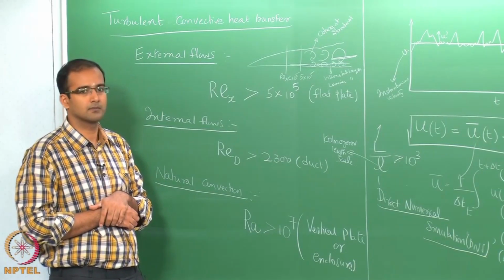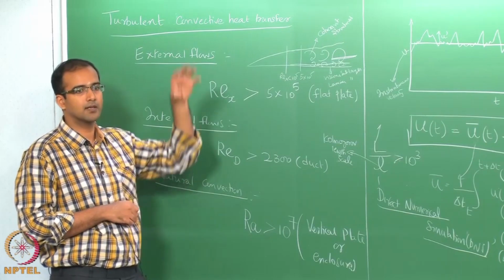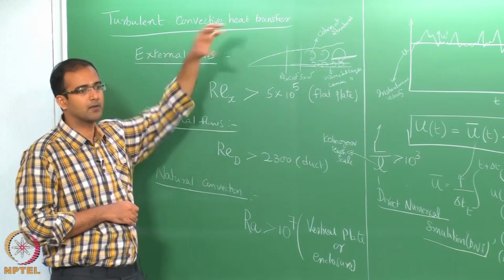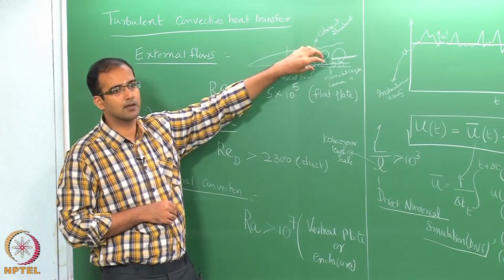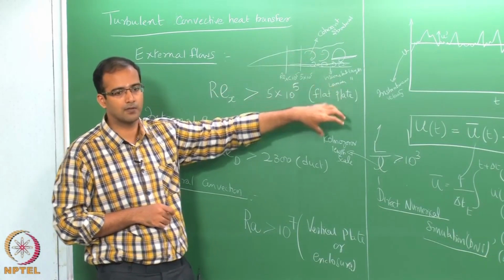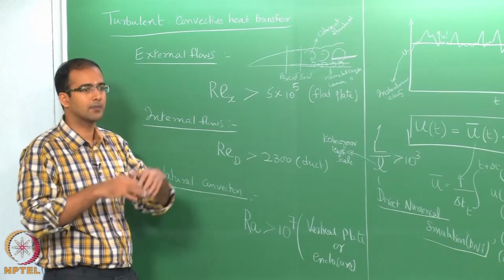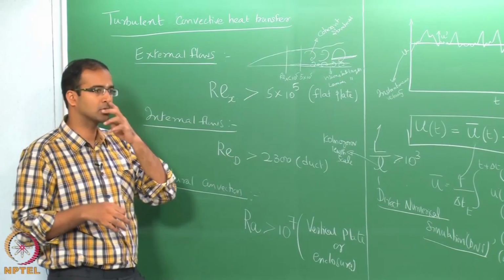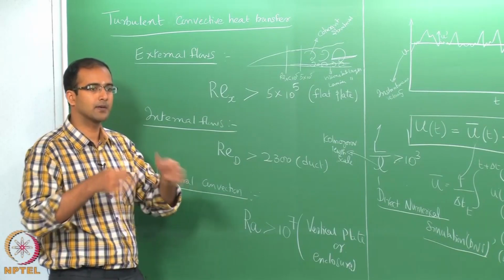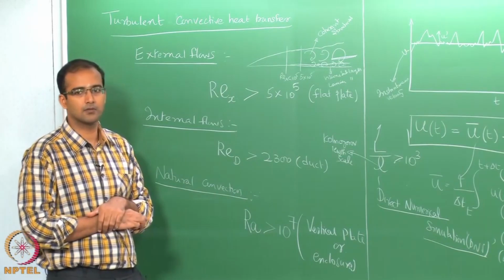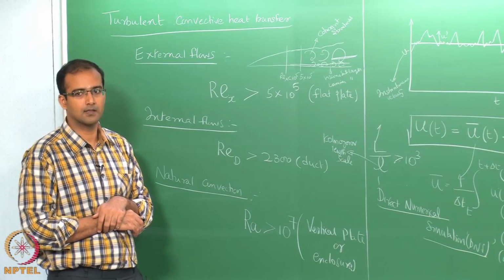dissipation. All this turbulent momentum coming from the larger eddies is handed over to smaller and smaller eddies, and finally the smallest eddy will dissipate this. There is nothing else to take away this energy from the eddy, so it dissipates itself into heat due to viscous dissipation effects at the wall.